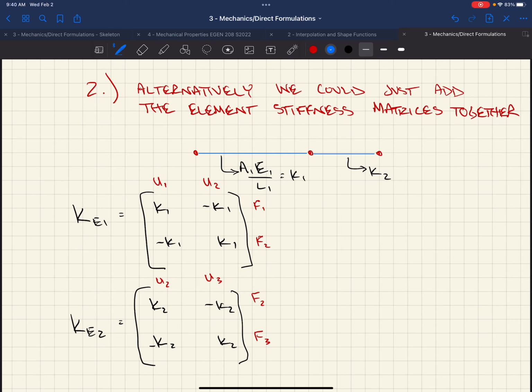So it would essentially be that you have a linear bar element to a nonlinear bar element. All that's saying is that that nonlinear bar element has a different assumption based on the displacement of that node versus the linear bar element. We used Hooke's law for our constitutive relationship. It might not use Hooke's law. It might use some other type of constitutive relationship.